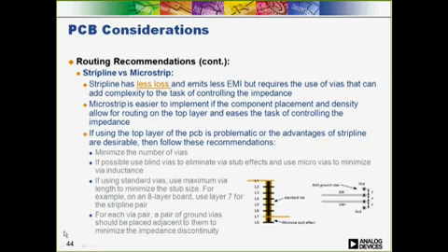Using the microstrip technique is easier to implement and control the impedance as long as the component placement and routing density allow it. Given the fact that the small addition of insertion loss on the microstrip can be compensated for using emphasis or equalization, I think there are more benefits to using a microstrip technique and staying on the top layer, as long as the board layout can accommodate it and the EMI is sufficiently managed by other techniques. This will enable you to minimize the number of impedance mismatches along the transmission channel.